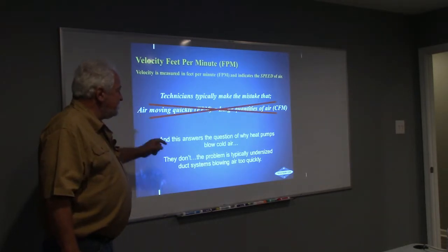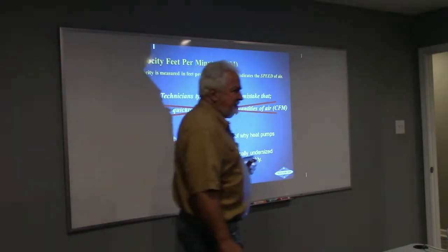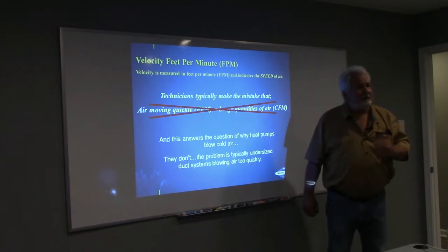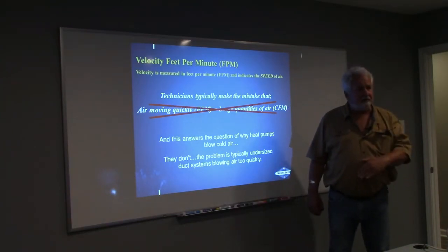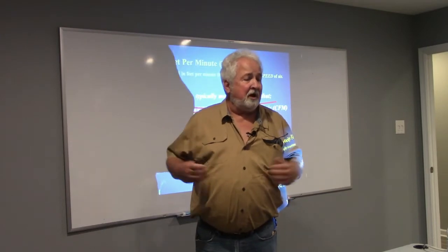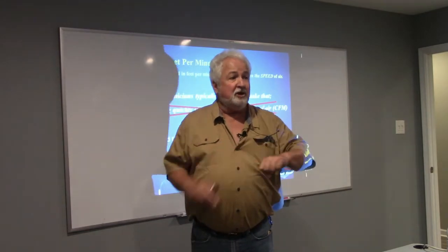That's not right. This answers the question of why heat pumps blow cold air. You've heard the customers complain, I hate heat pumps because they blow cold air. I'm here to tell you, no, it's not. It does not blow cold air. You've got your ductwork undersized. Let's prove that out. What's the temperature of the air in your lungs? 98 degrees? Okay. Let's take 98 degree air and move it through a large duct onto the back of your hand. Come on, you guys can do this. What you got? Warm air? Yeah. Take that same 98 degree air, move it through a small duct onto the back of your hand.